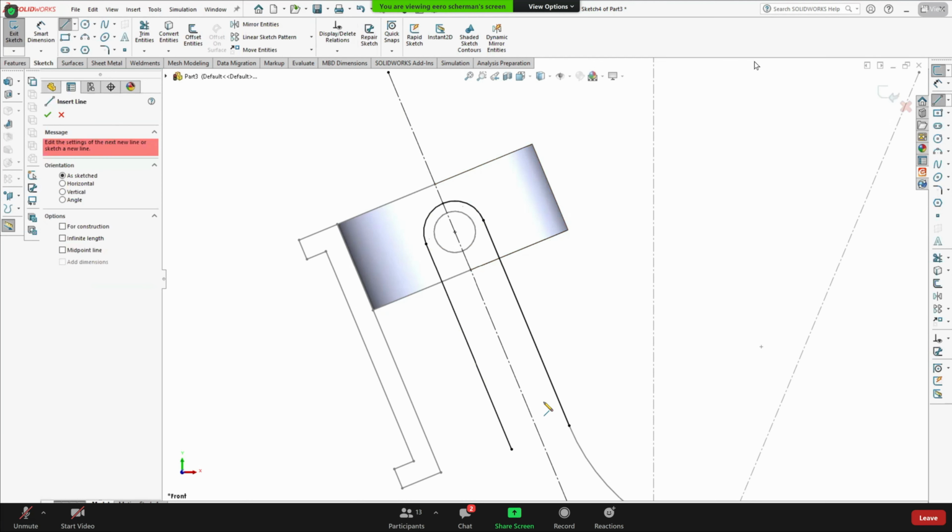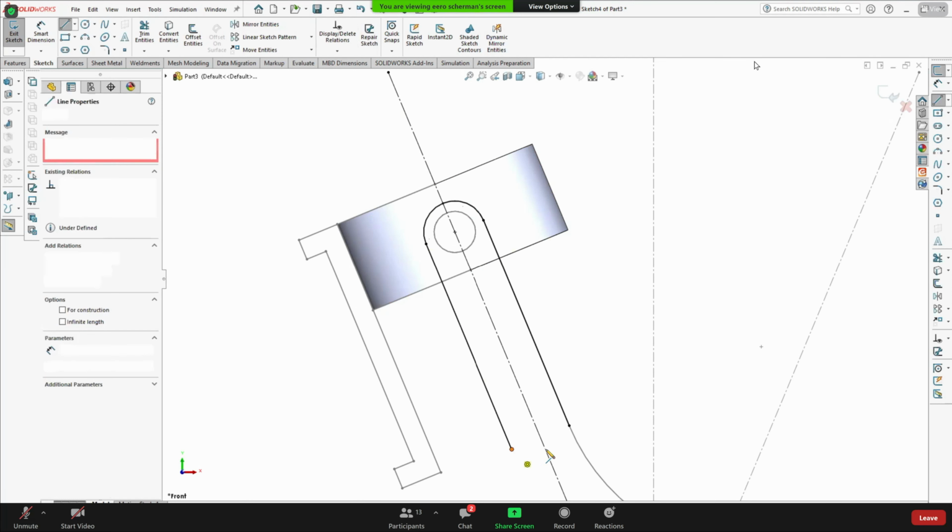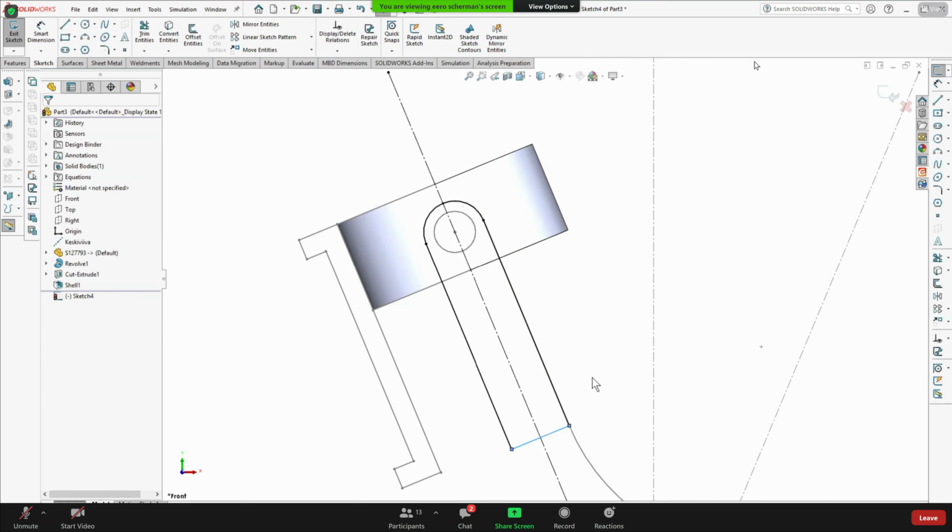It's best practice to try to avoid as much as possible drawing anything or adding any dimensions in this type of modeling. Because, for example, if I add a line here, it's not defined by any base sketch. But since the length of the line is derived from this edge of the connection rod, it might work okay.